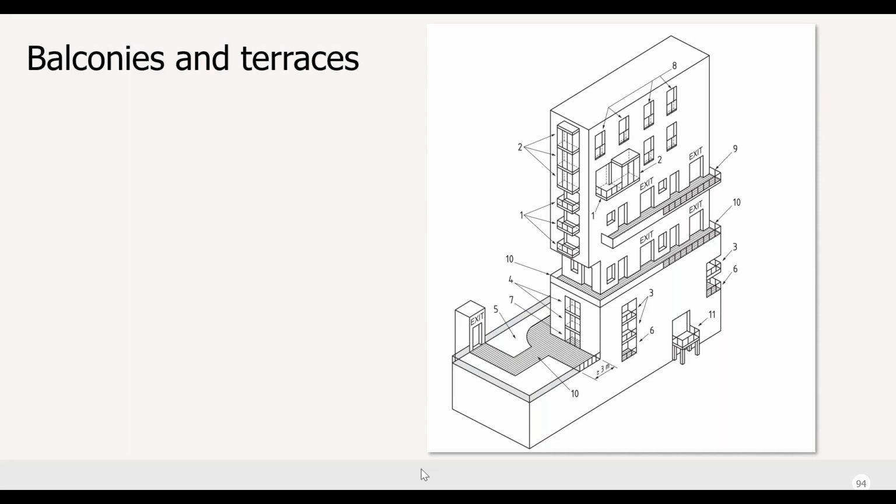And there are two generic methods of draining a balcony or a small terrace in a controlled way. Edge drainage, where water is collected on a surface and directed to an edge where it is thrown clear of the building, and pipe drainage, where it's collected on the surface, including at the edge, and directed via gutters and or outlets to pipes in the building drainage system. And as Mark detailed in his introduction, keeping the water away from the door back into the building proper is a very, very important point.